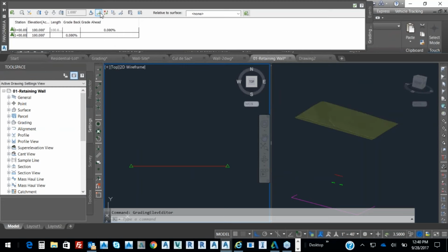If I look up here at the top, I can insert elevations, delete elevation points, grab elevations from the surface, drape my feature line on top of a surface. I'm going to be doing some of these things during the course of this quick 60 minutes. So something as simple as raising the elevation, I can move it up a foot every time. So just think about, we have to think outside of the box. If this was a rectangle, if this was a building pad, I can move this up 1/4 of an inch in increments. So a feature line gives you so much more flexibility.